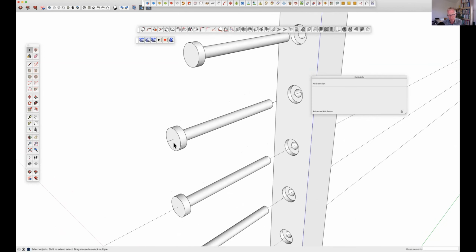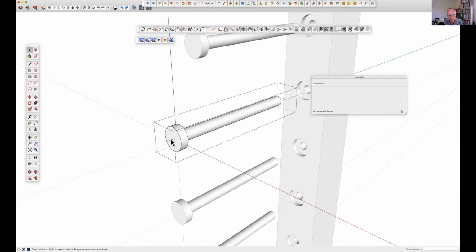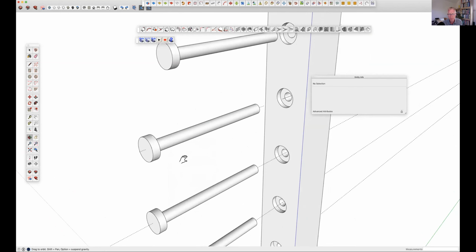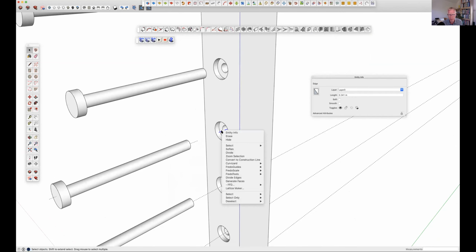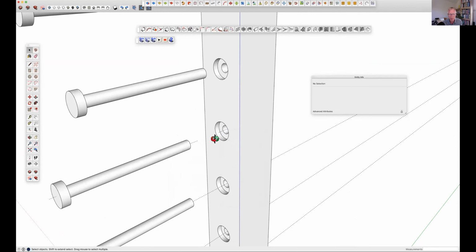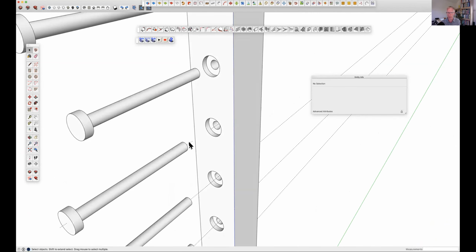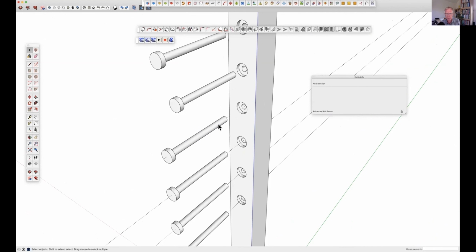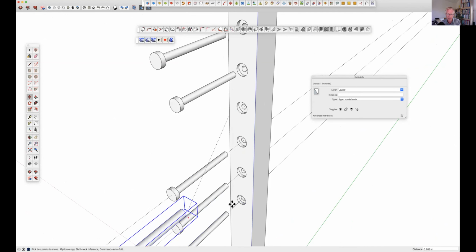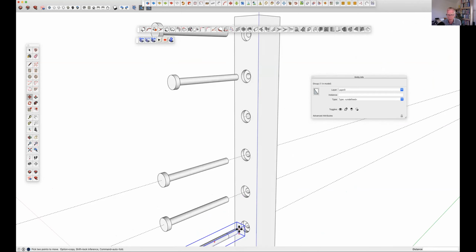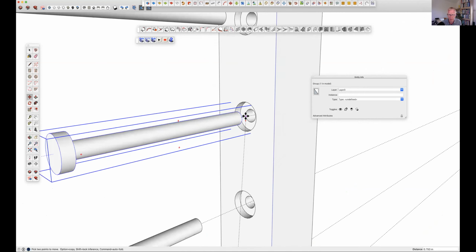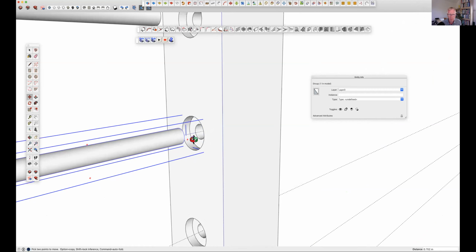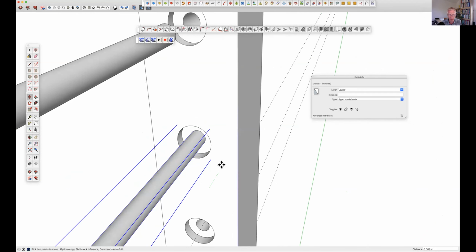A neat little plugin allows me to select these pieces of geometry and convert them into construction lines. And it's been around a long time, and I found it very useful, especially as guides get switched off when you take drawings into, sorry, into layout. It also means that I can take this geometry and I can then very quickly snap to other guide points for assembly or indicating that something is aligned. And then I can just slide it into position.